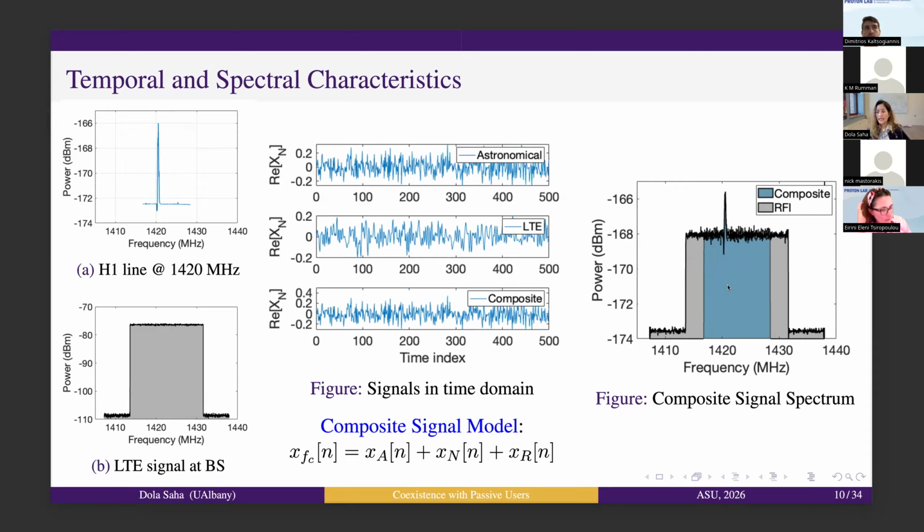and this is what we get in the frequency domain. Now, why don't we actually transmit the signal, and instead use a synthetic one? Because 1420 megahertz is a protected band. It's not just a license that someone can give us as an experimental license. This is a protected band, so no transmission is allowed in that protected band. So that's one of the reasons. If we really want to do a superposition of two signals, one can be captured truly from the radio telescope antennas. The other one is synthetically generated. And that's what we have to start with.